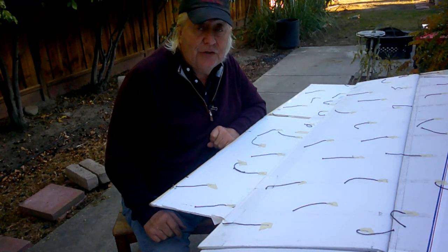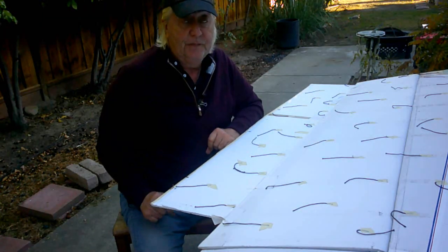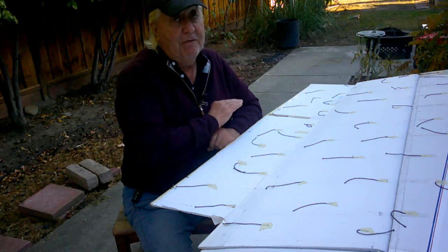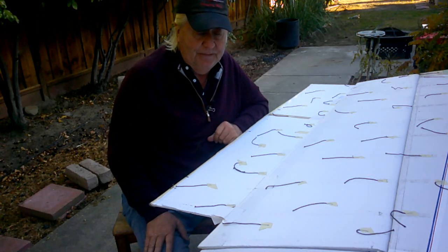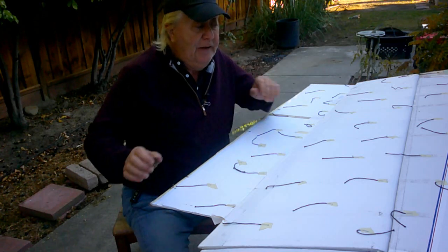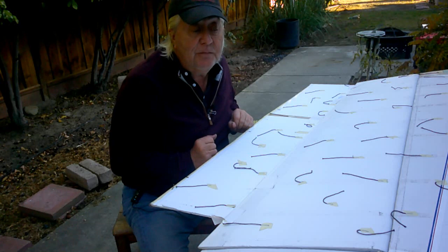You have the Swift, which has the elevon cut out of the wing. It works too. Super design, flies fantastic. Plenty of controllability on that. Okay. This one, elevon cut out of the wing, doesn't work. Massive problems with flow separation.